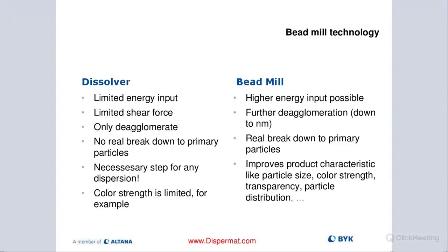Or a horizontal bead mill, if the particles are too large, they're going to sit there at the end of the back part of the milling chamber, not able to go through the dynamic gap or the screen. So you're going to clog up your mills. So it's very important that we pre-disperse first before we actually start the milling process.